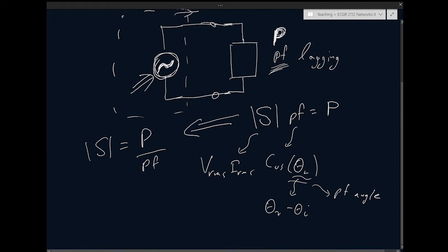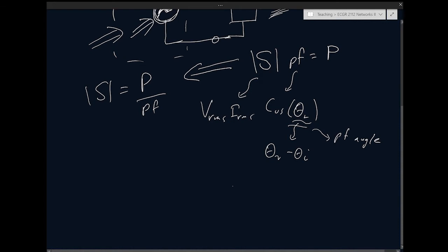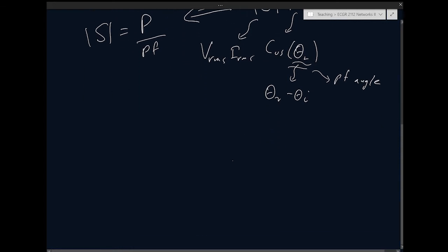sources of power, typically like your utility or any entity that provides power, do not like a power factor that's lagging too much. Why? Well, let's say we have the load, right? What does it mean for, like, let's say you're drawing 100 kilowatts. And let's say the power factor is bad. The power factor is 0.5. Horrible, right? What does that mean?